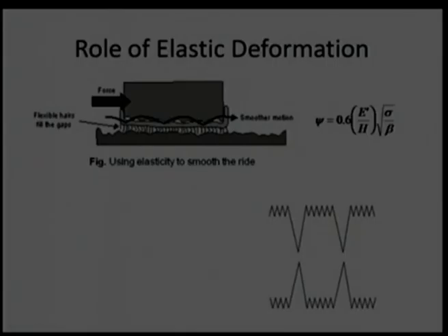First, if the surface roughness value is high, as the typical figure shown here, you can see the peaks and valleys, and certain peaks coming out are harmful for the machine component. If the surface roughness is higher, naturally the plasticity index will be high, and because of the high plasticity index, there will be some deformation on the surface.